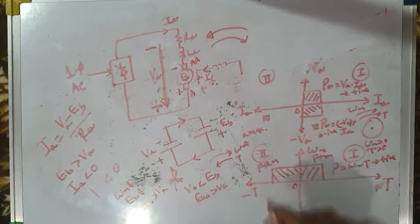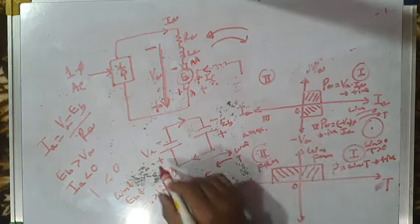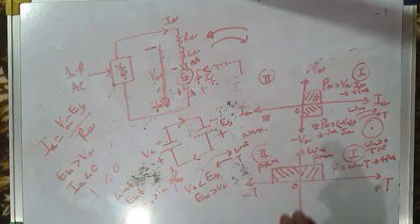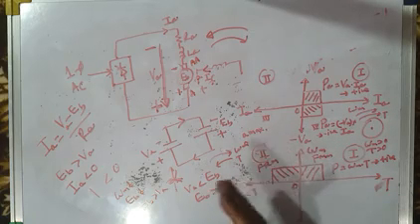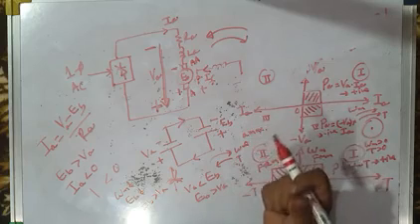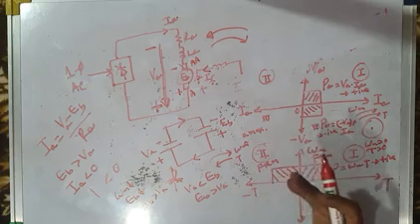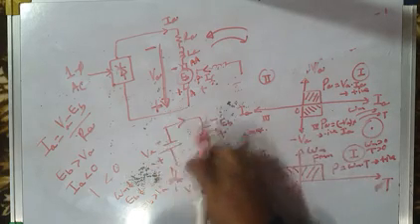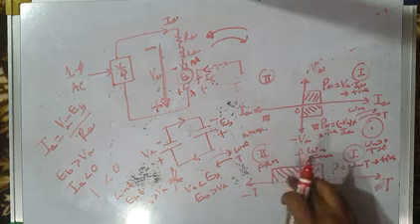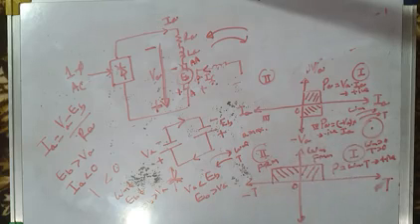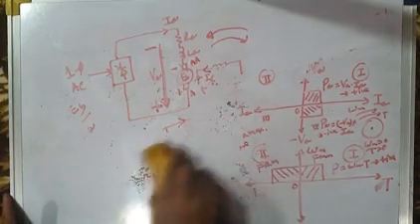Okay, so therefore in the forward regeneration mode, using the phase controlled converter, you can slow down the motor and you can also stop the motor. It's not used only for halting or holding the speed, slowing it down. You can use this converter for slowing down the motor and the drive, and also stopping it, bringing it to standstill. Fine. So this is one way of understanding it.